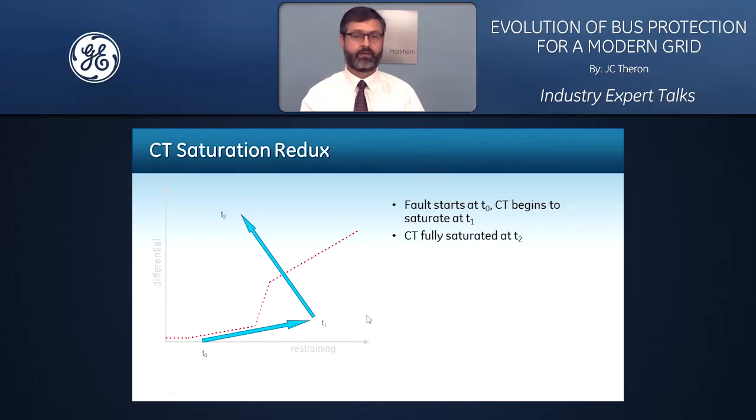Let's have a look at what happens during CT saturation based on our differential characteristic. Typically at load conditions, at time t0, we will have very little differential and a little bit of restrained current based on load conditions.